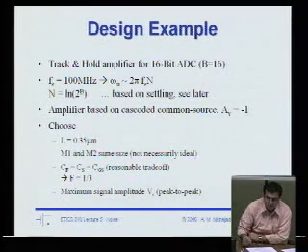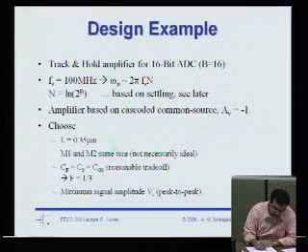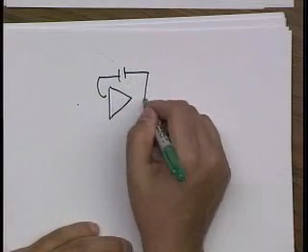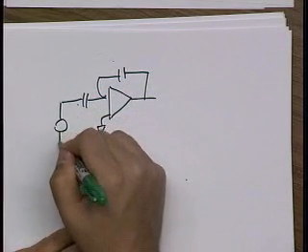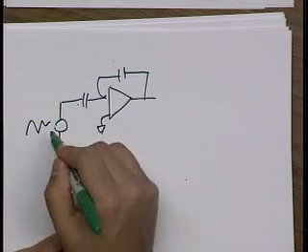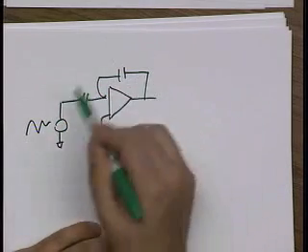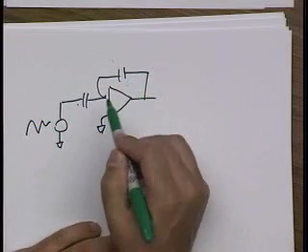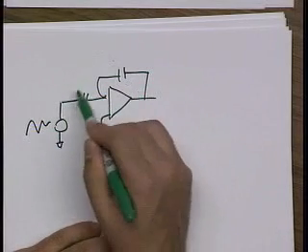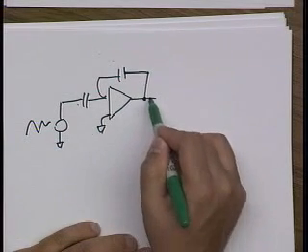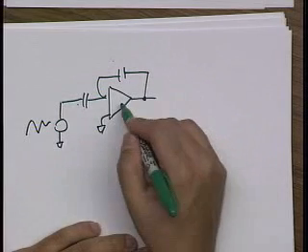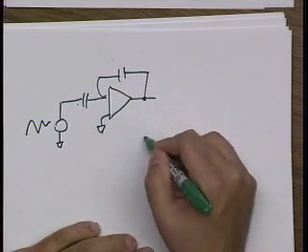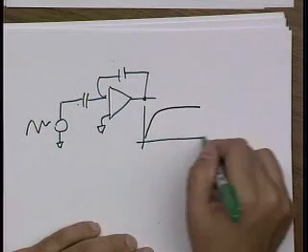Well, because there's a settling time issue, the idea is that I'm going to have an amplifier with some feedback in it, and what I'm going to do is the input is changing continuously. I'm going to only run this circuit in discrete time. So at one discrete instant, I'm going to charge up this capacitor and then transfer that charge here and produce an output voltage. We're going to talk a lot more about these circuits later, but the idea is that because of the settling time of this circuit, it's going to look something like this, the output voltage.